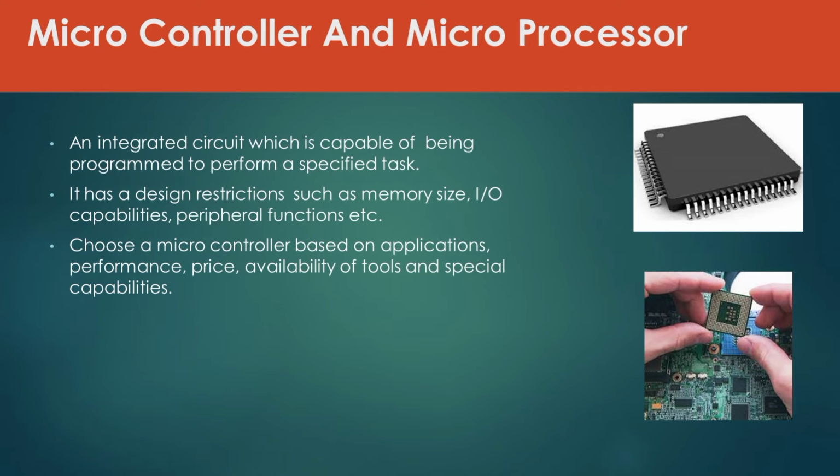Microcontroller and microprocessor. Microcontrollers and microprocessors are different ways of organizing and optimizing a computing system based on a CPU. While a microcontroller puts the CPU and all peripherals onto the same chip, a microprocessor houses a more powerful CPU on a single chip that connects to external peripherals.